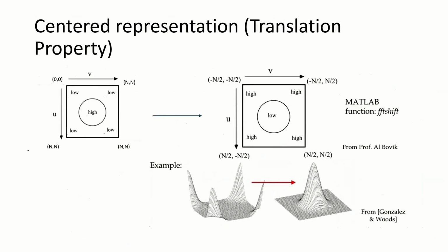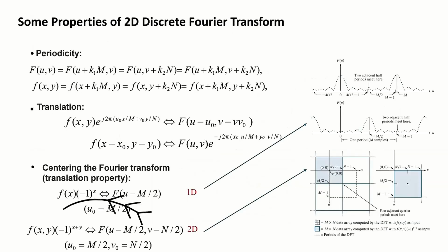Okay, here if we do this shift in the frequency domain, then this same shift will reflect in the spatial domain. This is what I told you. The shifting in frequency will be this. So when I'm saying shifting, I'm not shifting the frequency domain. In reality, I have to do this to make the shift happen. See what I'm saying? This is computationally much better because I just have to multiply with 1 or -1 depending on the value of x, or in 2D x plus y. This is much better as compared to shifting, because if I do the frequency domain first and then shift, it is difficult, mathematically and computationally inefficient.